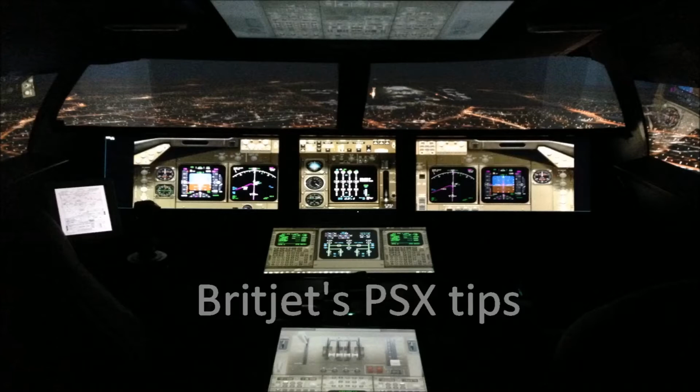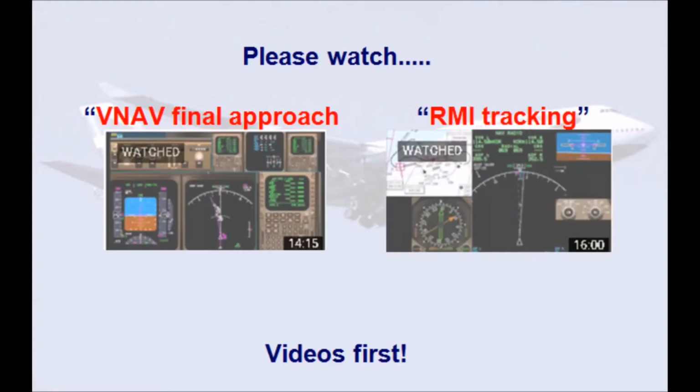Today, the first of two videos on non-precision approaches, as they used to be called, nowadays called non-ILS database approaches using an FMC. This one, NIDAs then. Approaches which are in the database, but which are not an ILS. Before you continue with this video, I highly recommend you watch Final Approach for VNAV and RMI tracking.